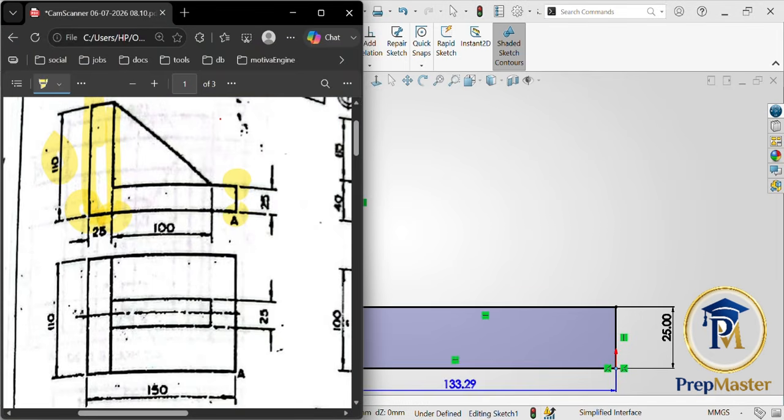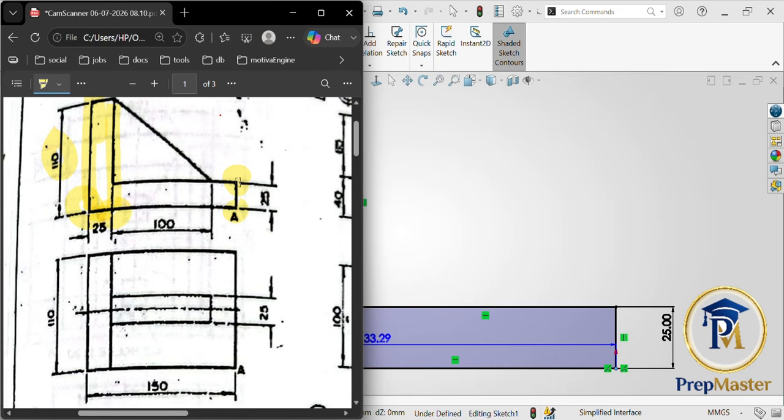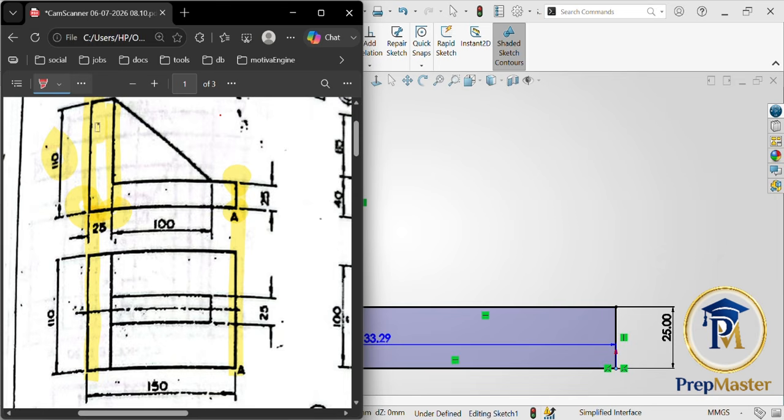So let's jump down to the drawing and get the correct dimension. One thing you can do with technical drawing is trace the outermost part of the drawing down to get that length, and trace the outermost point of the front view down again. Use a different color and a different pen.